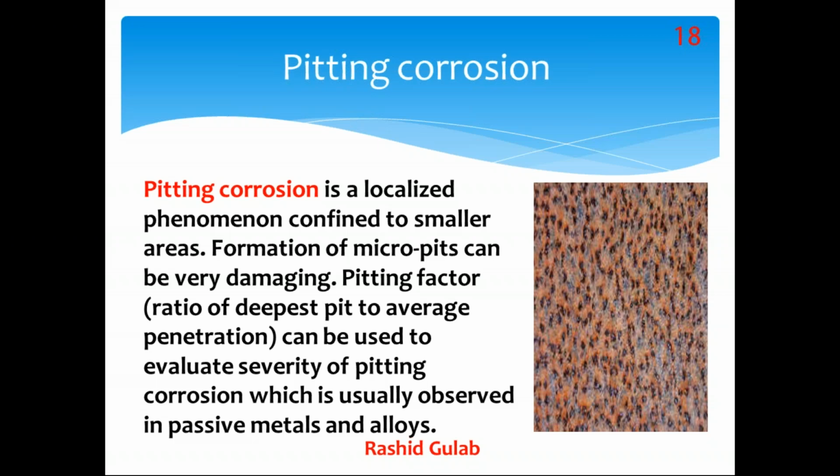If we find any pitting after the blasting with the naked eye, we are not accepting the material. Why are we not accepting? Because it is critical. I don't know how much depth this pitting has, up to where the pipe is already corroded. So the depth and the criticality, everything we measure through NDT, non-destructive testing. If the report is okay, then only we proceed to the next process. After blasting, we go for the painting. Otherwise, we will keep the pipe idle. We will not go for the painting.